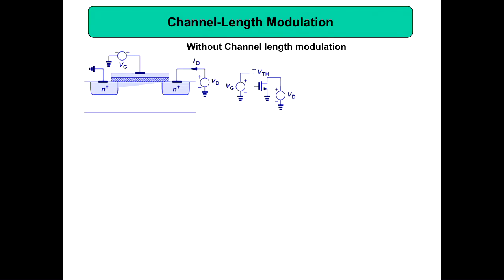When we look at the operating principle of the MOS transistor, what we have noted is that the electron concentration is not actually uniform across the channel. This is an NMOS. In the case of NMOS, the majority carriers in the substrate are holes, but you get a channel made of electrons. So in the NMOS, the channel is made of electrons, and the electron concentration is not uniform.